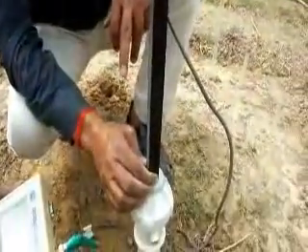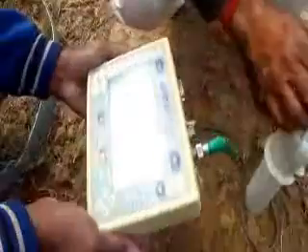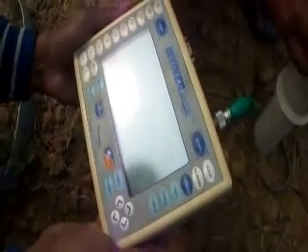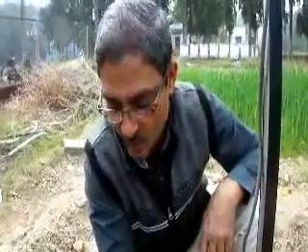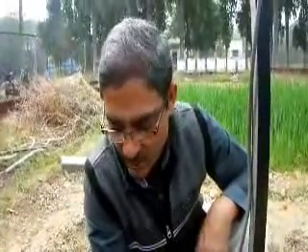So now in this way we have soil moisture for 30, 45 and 60 centimeter depth of soil by using the FDR method. It is in percentage. We got it from the tensiometer in terms of hydraulic head or suction head, and we used the gravimetric method to compare these three methods of measuring soil moisture or soil potential, to find out whether this is sufficient moisture for crops for practical purposes or we need to supply irrigation. So in the next experiment we will learn how and how much irrigation we need to supply by getting the information about soil moisture.